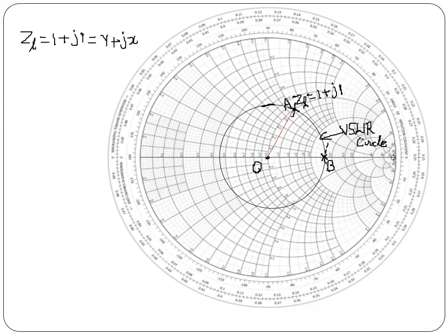You can see in your Smith chart, in this figure, the value of VSWR is 2.6. The VSWR circle cuts the center horizontal axis, which coincides with the R circle of the chart. That point is the VSWR value, that is 2.6 in this problem.